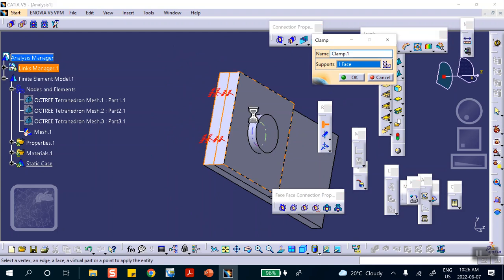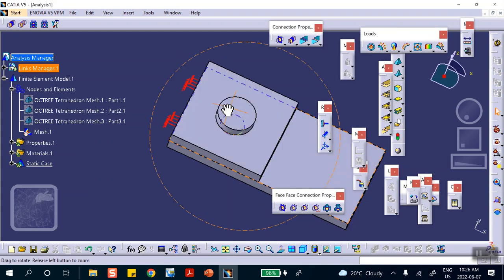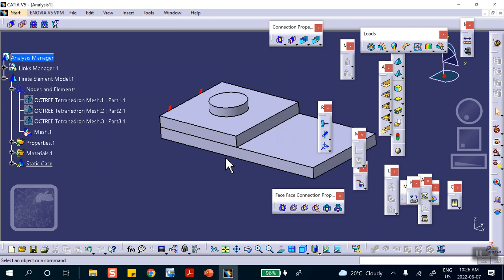So first of all, this end is clamped and that end is clamped. And the top plate does not go through the bottom plate. That's what I know. Okay, so I'm going to create a connection between the bottom of this and the top of the other plate and make that contact. Unless you're specifically told these are perfectly bonded, perfectly glued, perfectly welded, which you make fastened, as if it was machined like that. But this is not. I bought 2 plates and put them on top of each other. One does not penetrate the other one.